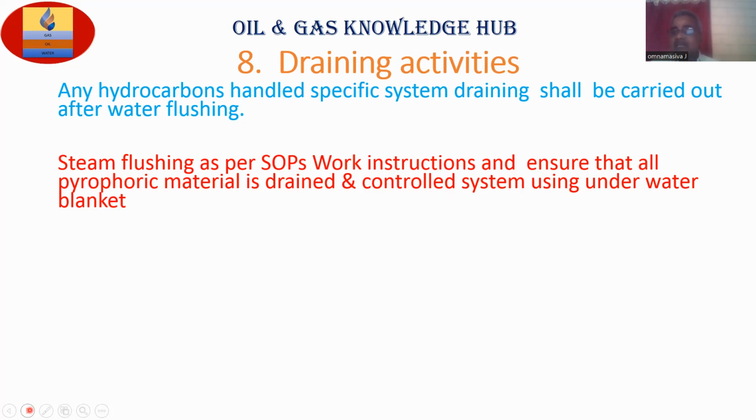Sour service, in the sense, is where H2S salts are there and the partial pressure shall be more than 0.5 psi. Then only it is considered as sour service. Here we are learning one more point, partial pressure. If it is less than 0.5, it is called sweet service.